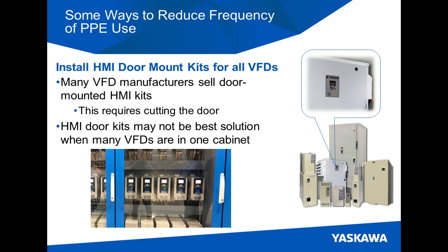However, installing these door kits often involves the added expense for specialized hardware from the manufacturer to mount the HMI, and as I said, it requires cutting the door. This also may not be the best solution if you have, as I show in the picture here on the bottom, a lot of VFDs installed in a single cabinet.